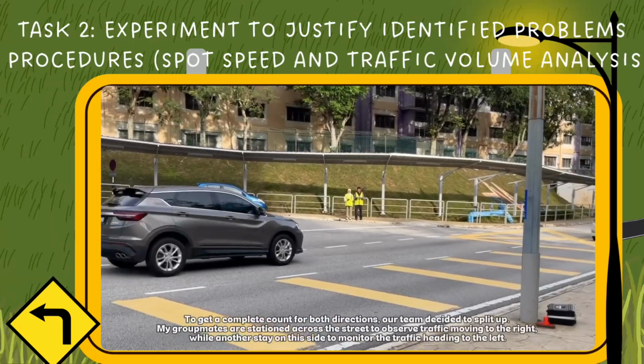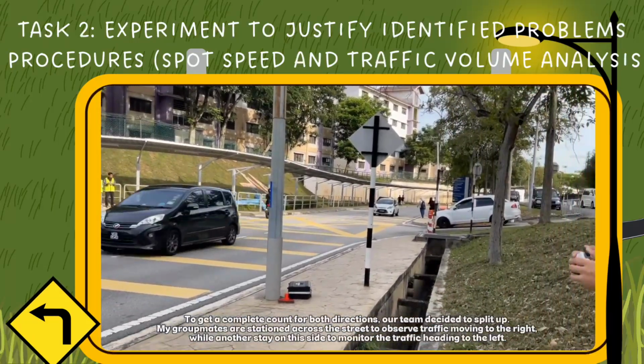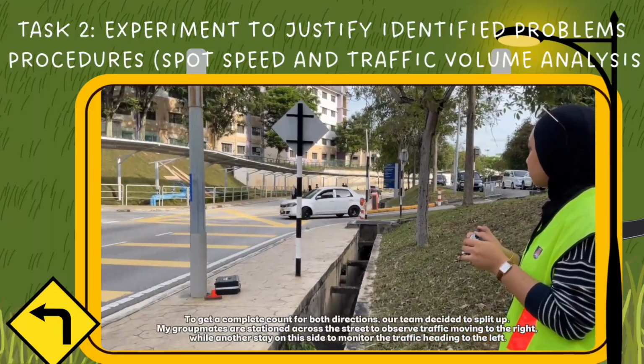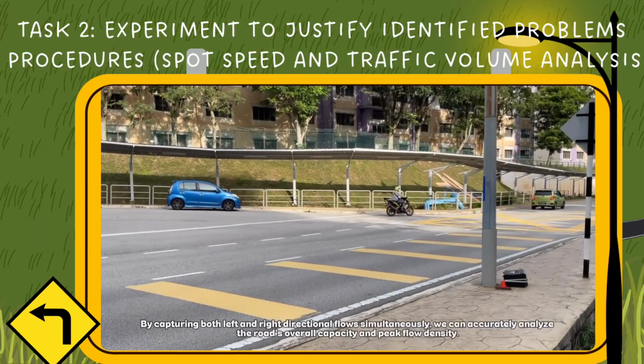To get a complete count for both directions, our team decided to split up. My groupmates are stationed across the street to observe traffic moving to the right, while another stays on this side to monitor the traffic heading to the left. By capturing both left and right directional flow simultaneously, we can accurately analyze the road's overall capacity and peak flow density.